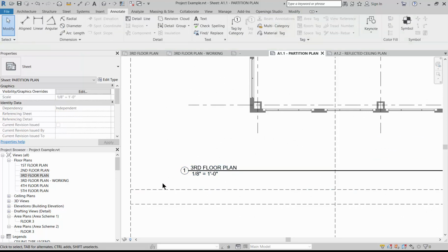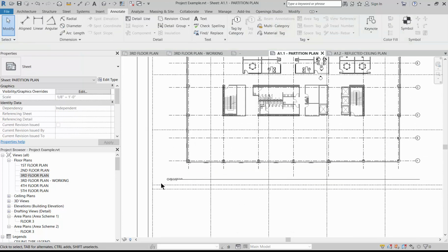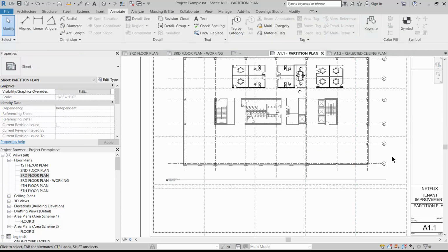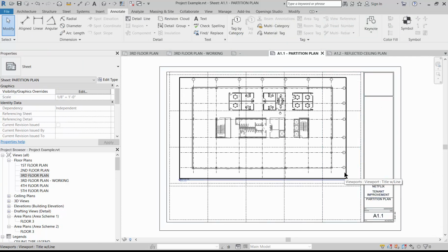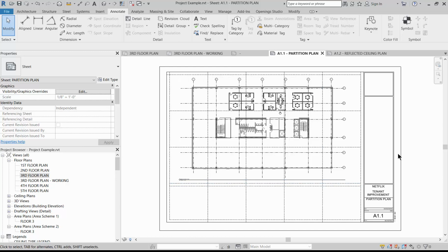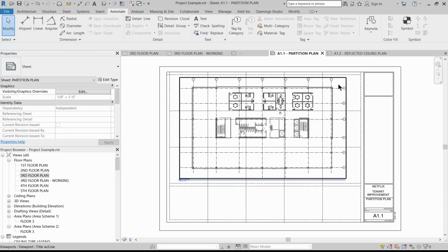Now, before I get into the details of the tile, there are a few things I do want to point out. Once you've decided on your first sheet exactly where you're placing your floor plan, you want to make sure that it's placed in exactly the same location on all of the subsequent sheets. I also like to use hidden lines for that particular purpose. You can use hidden lines to note locations of your grid lines if you have them, or the corner of your floor plan.